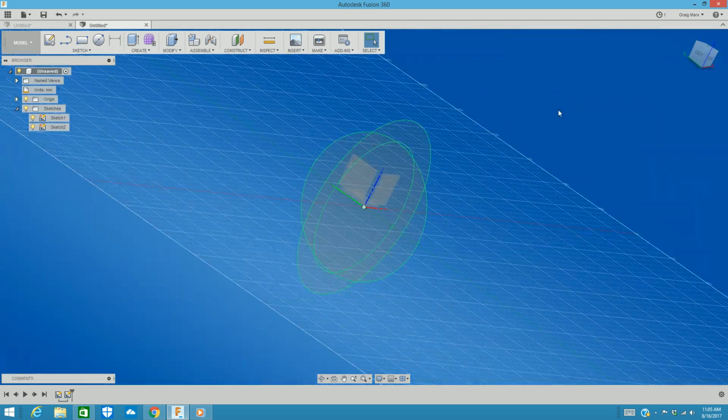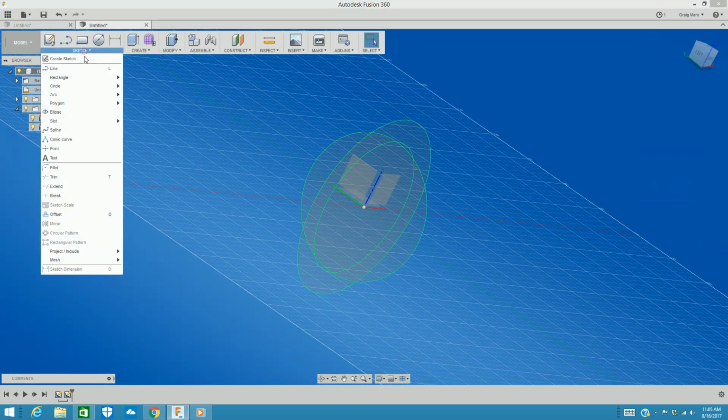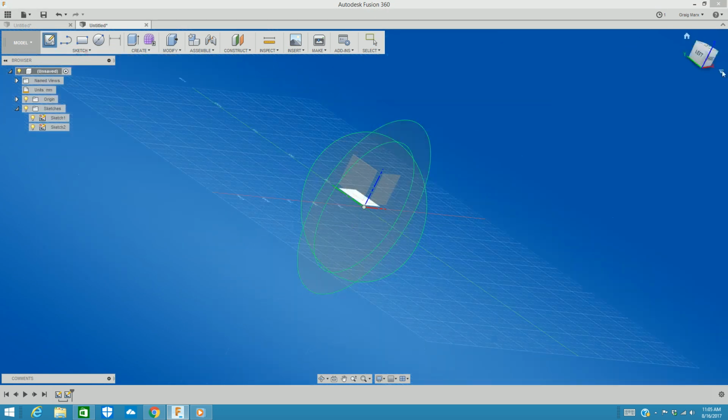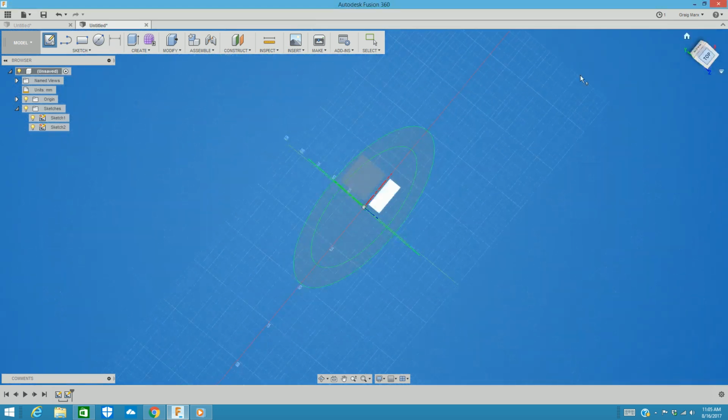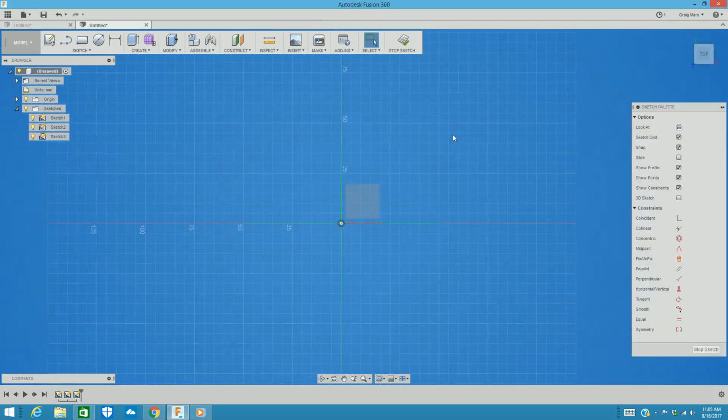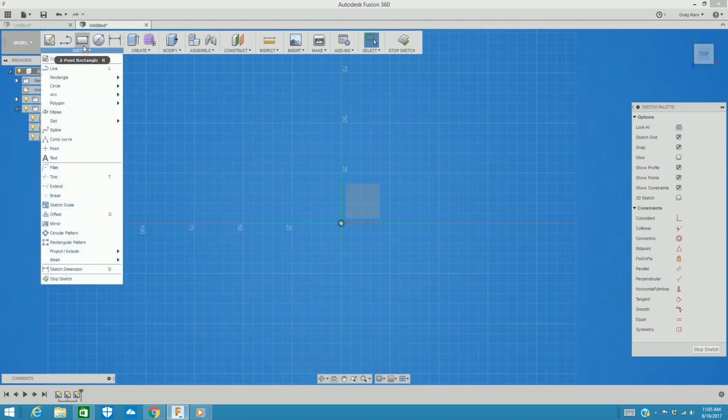All right. So we'll go to a new icon, sketch. I'm going to create a new sketch, and this time I'm going to work on the plane I haven't worked on yet, just to give you an idea of how I can make more shapes. And under sketch, I'm going to go ahead and look at spline. Splines and arcs are ways that we can make lines that are curved. So I'll give you an example of maybe what shape I want to make.